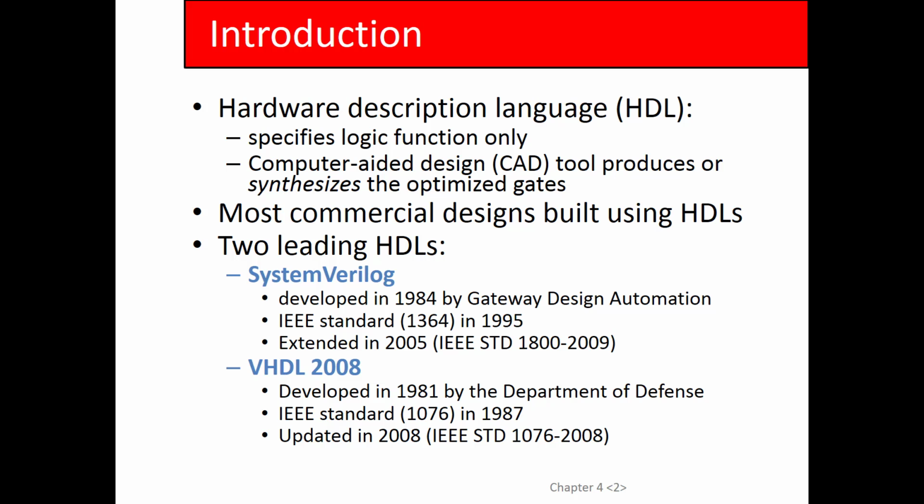The other problem is that hardware description language is a high-level language. You write it like a high-level language in a text editor, just like you do Java or Python. But as you write it, you have to think about the circuit that it will generate when you synthesize it. You may have to write it in a way that's pipelined, where you're breaking things up into multiple cycles, or you're cognizant of the path delays. How long of a data path will this generate? Will it exceed my setup time constraint?